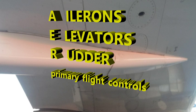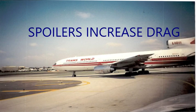Now, there's also what can be considered part of primary, helping a little bit, which is your spoilers. Your spoilers are there to help with spoiling the flight of the aircraft. So it's going to create some drag, but it has a couple of different functions. One, they can function as ground spoilers, and that has to do with coming in for a landing. And then you have some spoilers in flight, depending on the condition at any given altitude in the air.